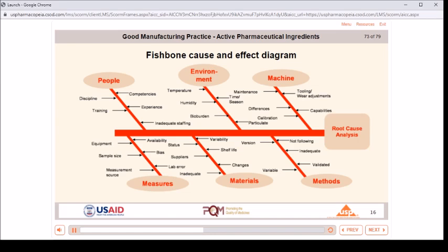Two, employees of the beta-lactam manufacturer did not change into factory scrubs and were allowed to wear their street clothes under their factory clothing, which, for many of the employees, were lab coats. Three, the two companies used the same laundering service for their factory clothes. This immediately resulted in the suspicion that residues were being introduced into the API facility by the employees on their factory scrubs and by the laundering company, which might be causing cross-contamination if their procedures were not appropriate to prevent it. The laundering company had never been audited.